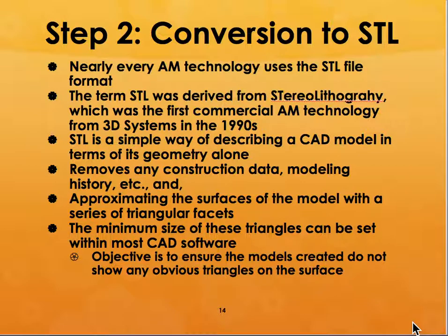So step 2 is to convert this CAD model to two-dimensional slice data. So why do we call it STL? STL was originally derived from stereolithography, which was the first commercial additive manufacturing technology from 3D Systems.